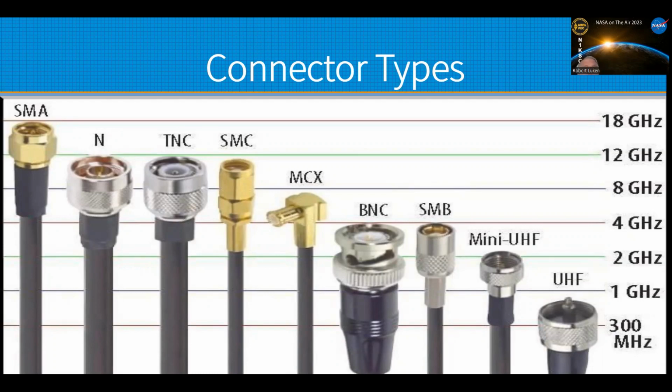There's your typical BNC, which most test equipment, unless it's really specialized or high frequency stuff, uses. Oscilloscopes, signal generators, all those kinds of things are typically BNC connectors. Those are very easy to use. It's a quick disconnect. It's just a twist and it locks. And everything in an airplane is BNC. They're good to 4 gigahertz. Test question.